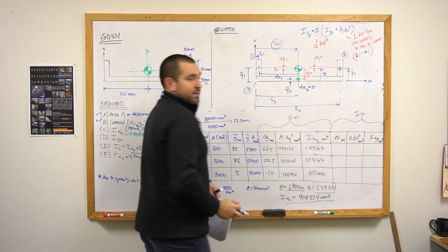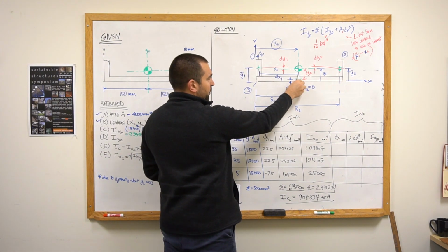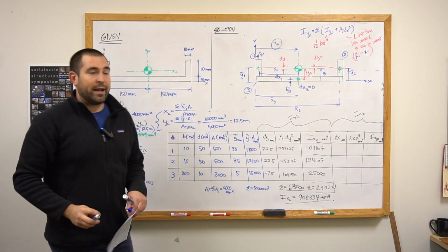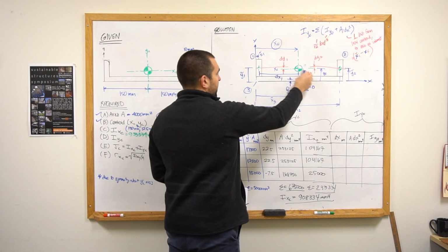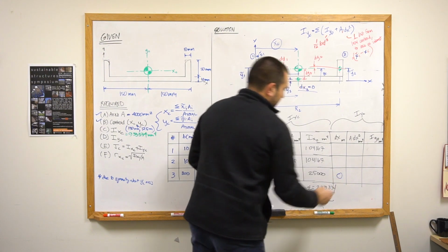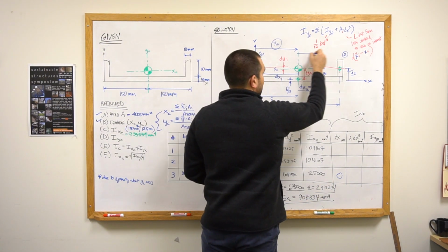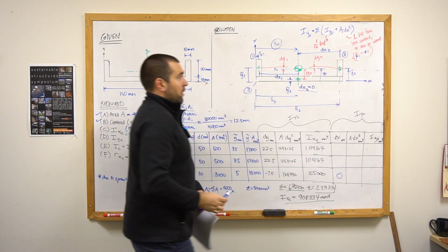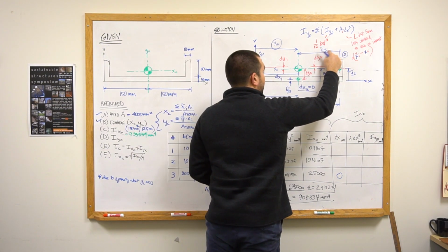dx3 is simply equal to 0. That's because the local centroid of this bottom shape 3 is in line with the overall vertical axis that we're taking the moments of inertia about. So there's no perpendicular distance between them, so that's just going to be equal to 0. That's a super easy one. It's nice if we can get zeros in these tables. And then finally, this distance here is dx3. Oh, sorry, dx2. That's shape 2 on the far right-hand side.